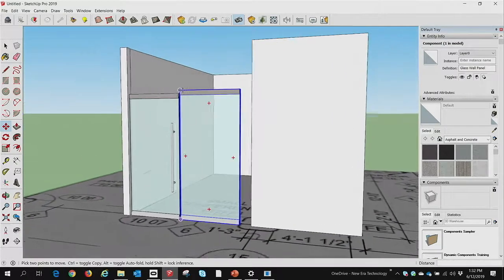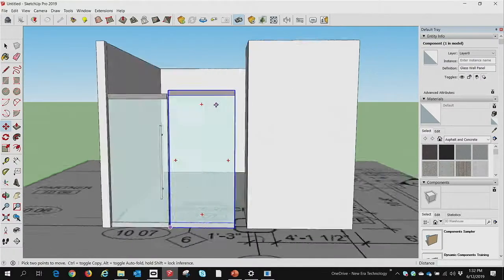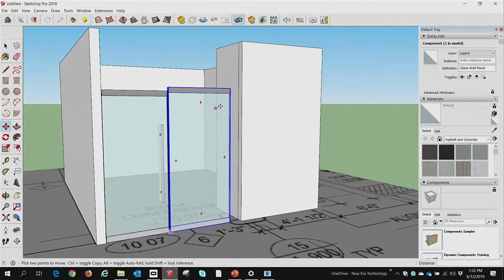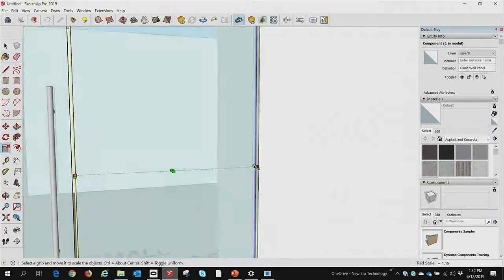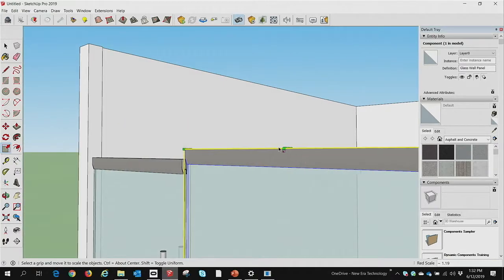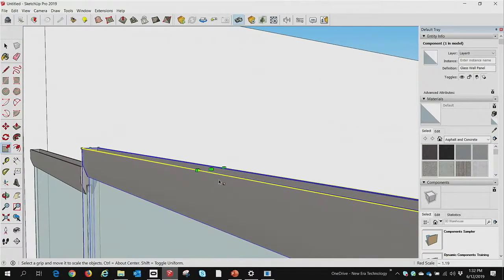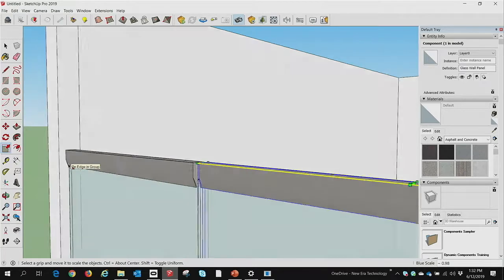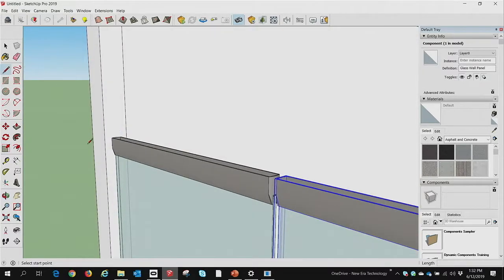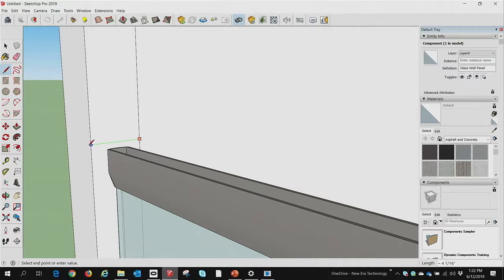So as you can see, the wall is a little bit taller than the door. I want to match it to the door height, and I also want to make it wide enough to fit this space. So there's a scale tool here that allows me to drag it over to make it the right width. And it took me a while to realize this. I've been working with SketchUp for about 6 years, and it took maybe 2 years to figure out that when you're resizing something, you can easily snap it to other objects, which is very helpful. So if I click the scale tool here, I can just drag over to the door and make it the same height there.